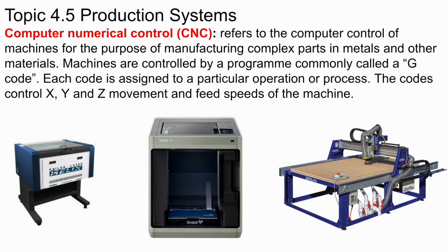And you can see here that we have two types of subtractive manufacturing and one type of additive manufacturing. So 3D printing is additive manufacturing. And when you put the G-code in the machine, it essentially tells the print head what X, Y, Z movements it needs to make and at what rate it should feed the filament into the print head. And that's what the G-code is.